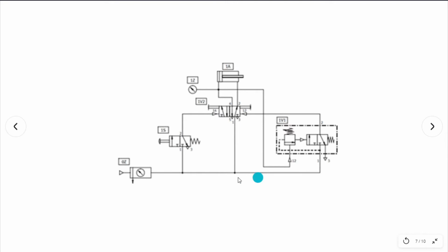As you can see in this example, you will have your supply, and then the supply will go to your input element and then your sequence valve. You have your final control element, and your power element will be your double acting cylinder. So let's analyze the circuit. First is your final control element. It is pneumatically controlled on both sides, and you also have an override so that you can override the final control valve manually. So it has a manual switch on both sides.